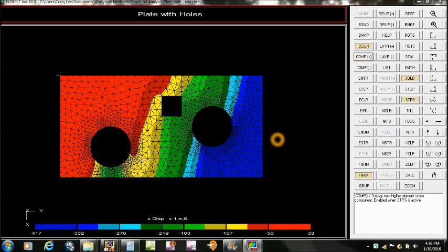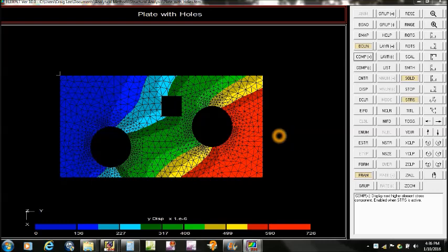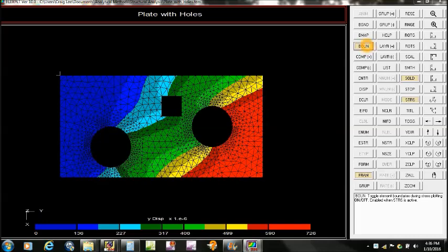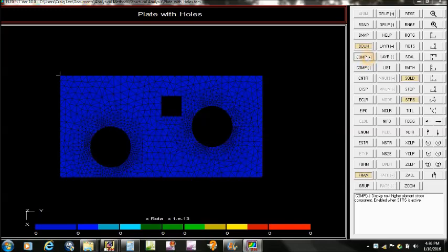We also contour the displacements. So this is the X displacement, so it's actually the lateral displacement here. And then we'll go one more. This will be the Y displacement, and that's the longitudinal displacement here. So the largest displacement was in the corner here. Okay, so we can keep doing that. We can also turn boundaries off here if it's easier to see what's going on with the element boundaries off. So let's go back to our von Mises stress here.